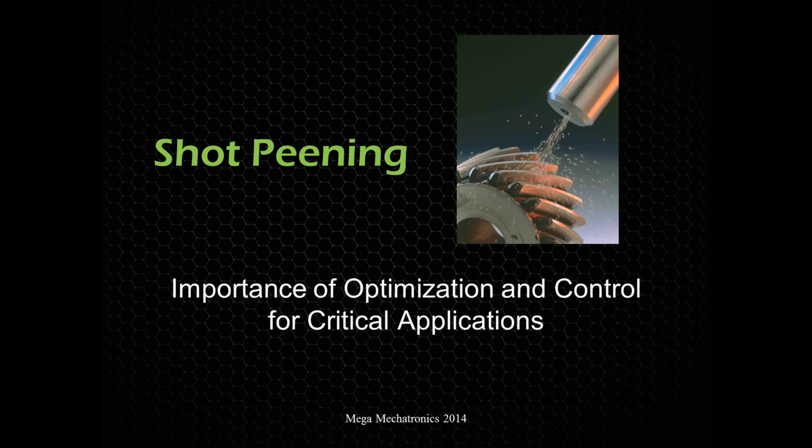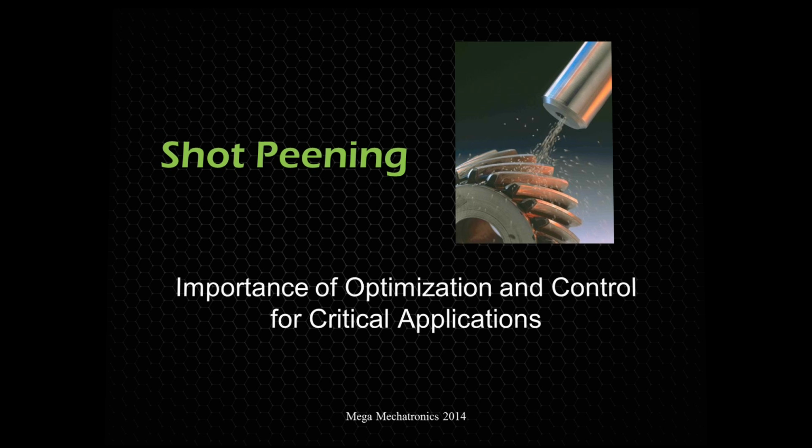And remember, shot peening is not shot blasting. This is not a cleaning or an abrasive process. We are using high specification material to impart residual stresses into the parts, and that's what we're going to look at.